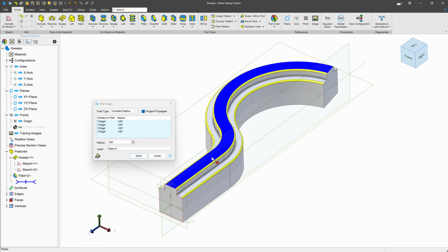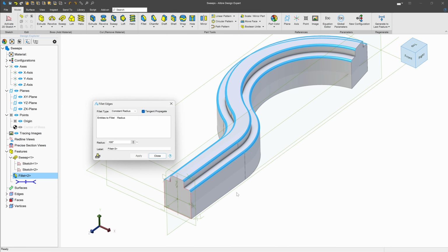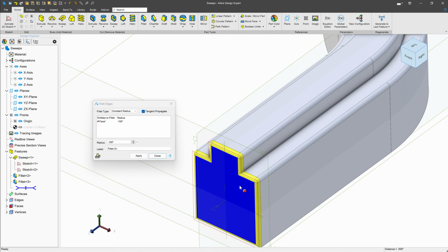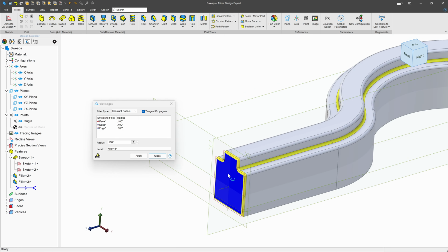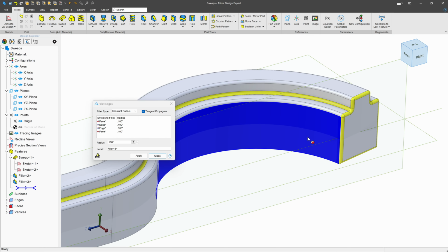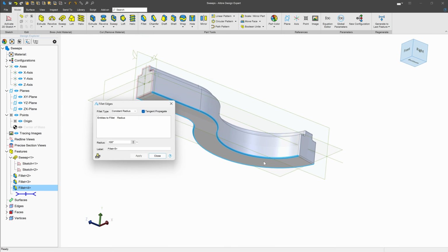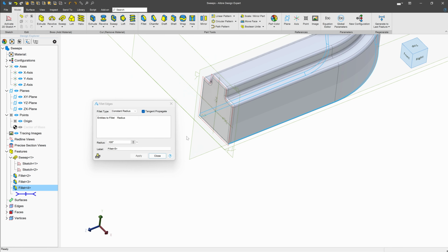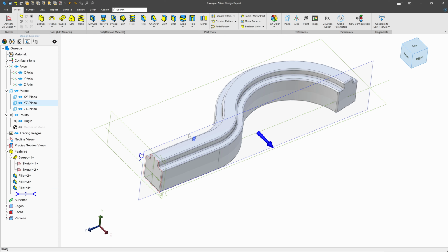And now you can say at this point, well, why don't you just do a sketch fillet on the sketch and you can get the same thing with your sweep? But I could not simply achieve rounded corners by clicking on this face and rounding out all of these corners on the face. So the fillet tool is very important because it can do more than just what we would accomplish by adding sketch fillets onto our sketch. Now when I click this bottom edge, we've been able to fillet just about every major corner on this model and have done so very easily. So that's one reason why fillets are so important.